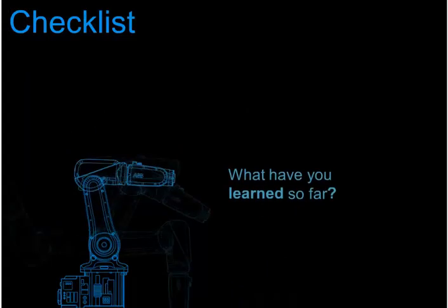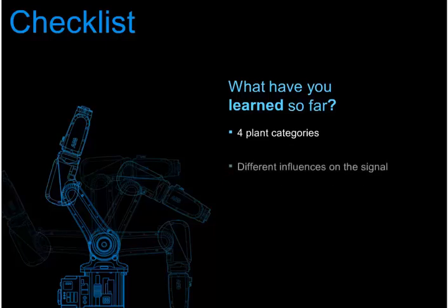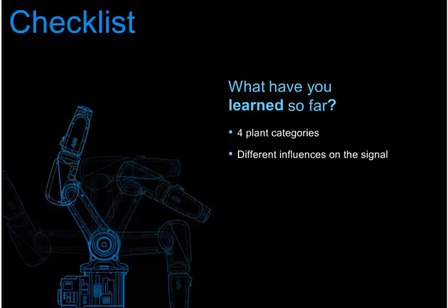What have you learned so far? Areas for WirelessHART networks can be separated into 4 density areas. The wireless signal will behave differently in a plant. It can be blocked, reflected, or scattered. This will lengthen the path it will take toward the gateway. RSSI, path stability and reliability are key metrics to rate the quality of a signal path. So far so good?